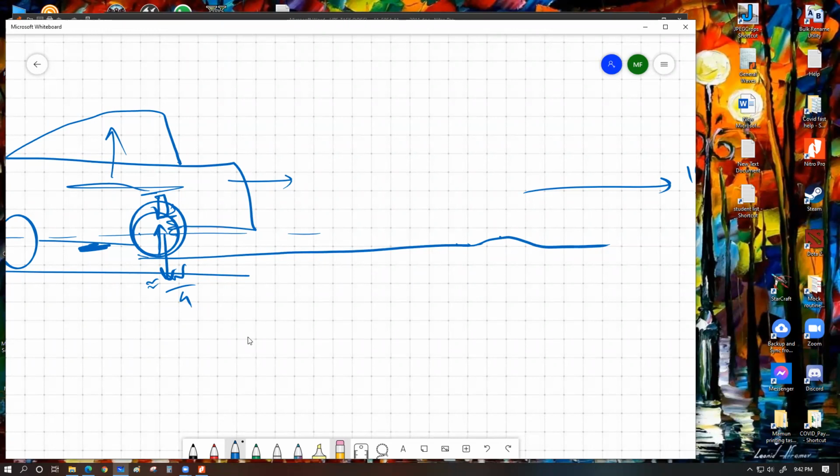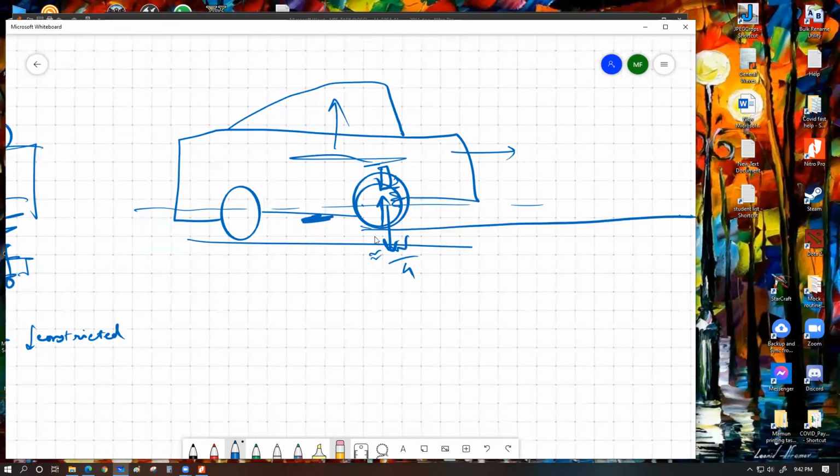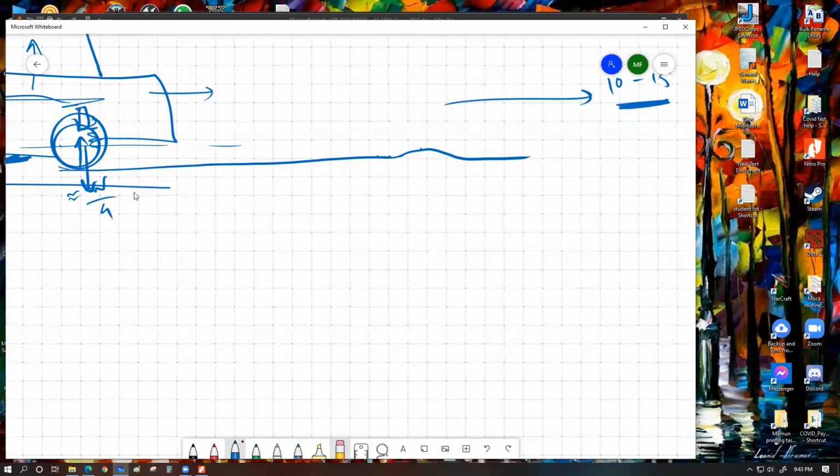Definitely, the wheel will come down, and as long as one wheel, or maybe two of the wheels, are in their upper position, the other wheels are going to balance with their individual shock absorber mechanisms, so that the car's entire body does not keep on vibrating. Whenever the car goes over a bump, the driver and the passengers will definitely experience one bump, but that one bump will not result in continuous jumping. If you don't have shock absorbers, only springs, after going over one bump the car is going to keep on jumping till all the energy is dissipated. That's something that we don't want to allow.